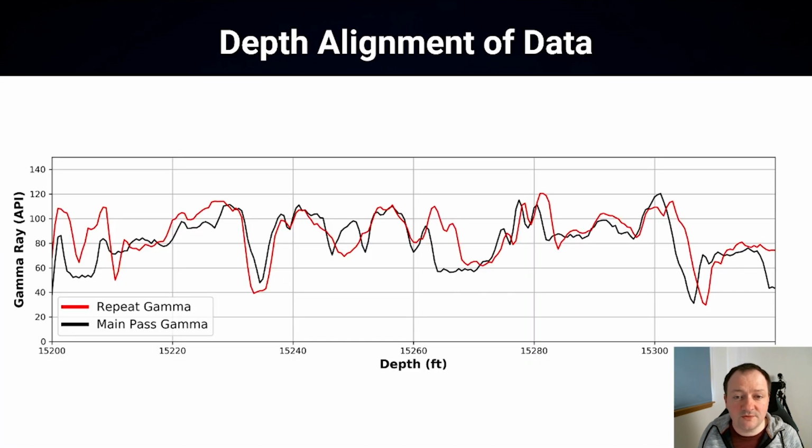So now we'll move on to one of the most important logging curves, and that is depth. Depth is a critical measurement that allows the successful development of a well or field. It allows the setting of packers at the correct depth, and it also allows us to perforate the reservoir at the right point. All well log measurements are tied to depth, and ensuring that logging measurements are on the correct depth is a key step in the QC process and for carrying out accurate petrophysical interpretations.